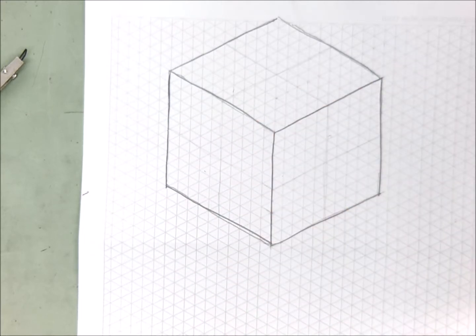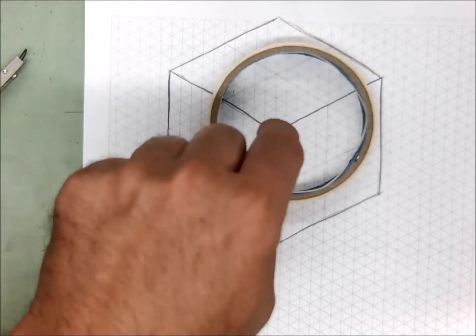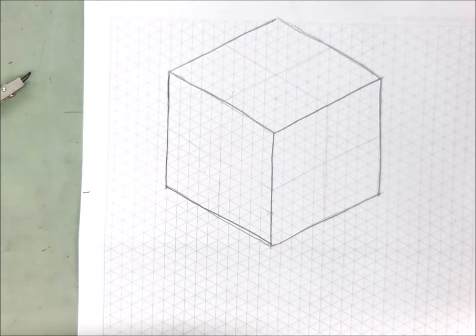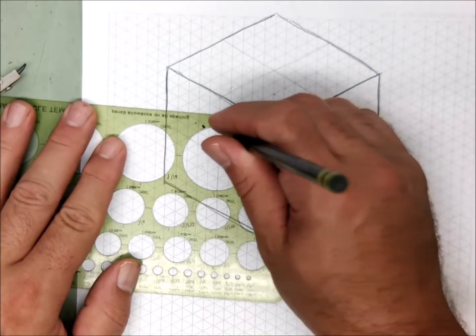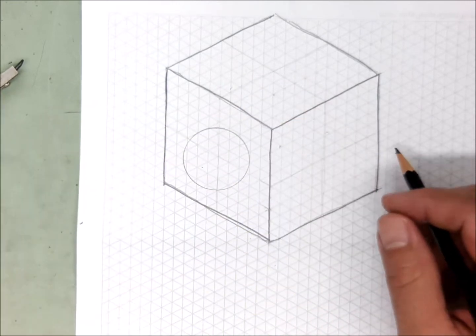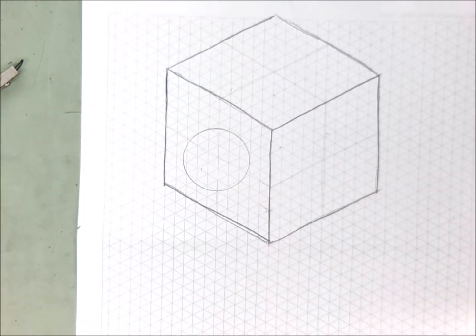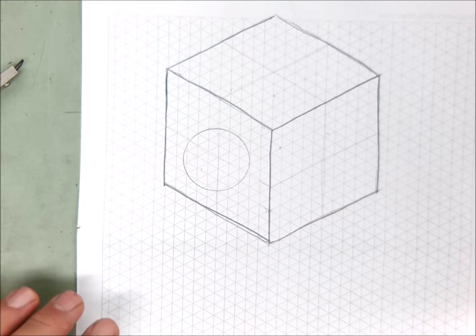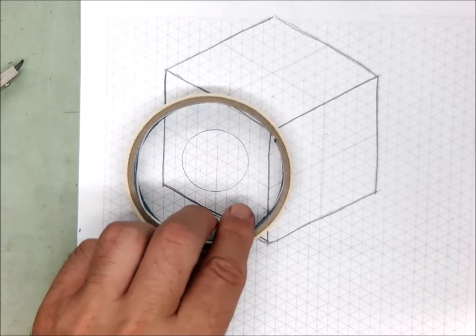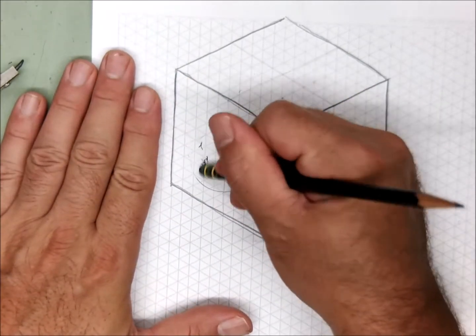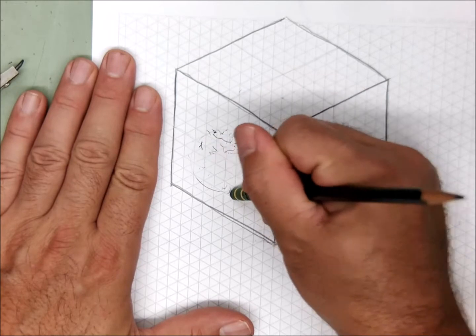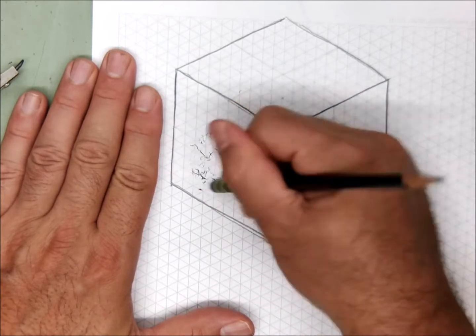Okay, and now what's the idea? Well, the idea is this hole that we drill is a round hole, but it doesn't look round in isometric. I mean, take a look at it. If you drilled a round hole, or drew a round hole in isometric, man, that looks messed up, or it should look messed up, okay? The circle is not round when it is tipped. It should be elliptical. So let's make believe that never happened. And let's get a retry, shall we?